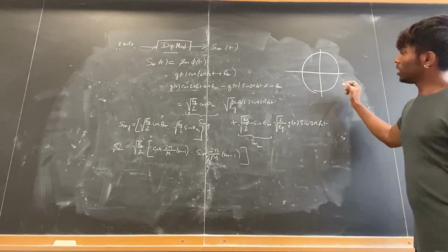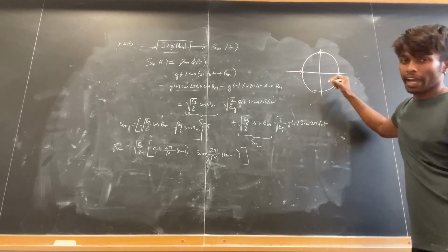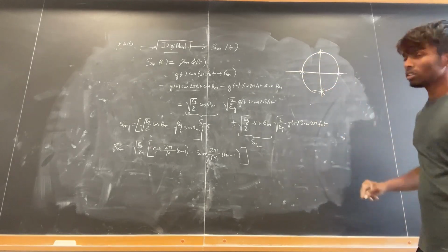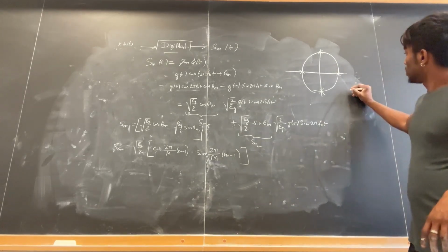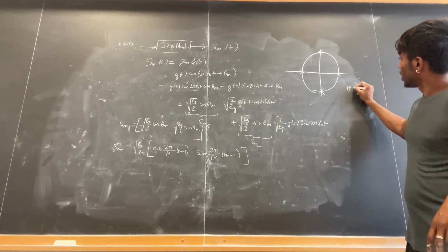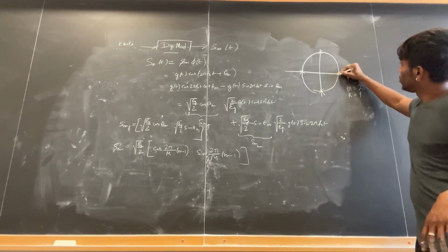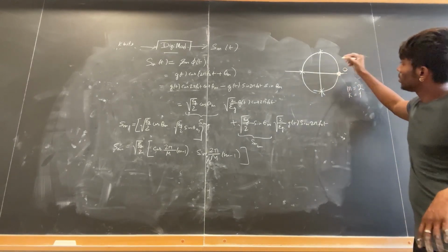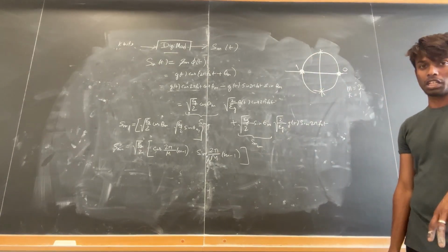So the first coordinate shall start from here, here, here in the anti-clockwise fashion, depending on how many m we are considering. Now we can consider only 2 bits. M is equal to 2, that means 1 bit representation. So it will be first symbol here, that is 0, and the second symbol here, that is 1. That is the idea of phase shift keying.